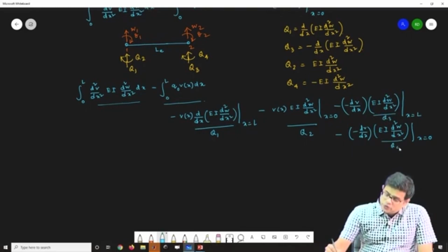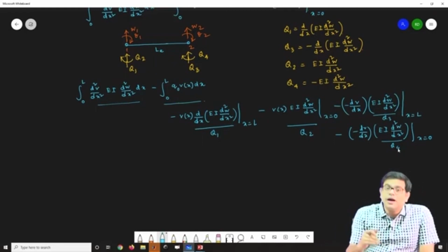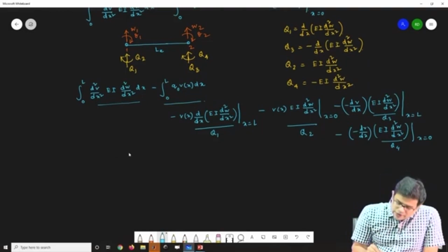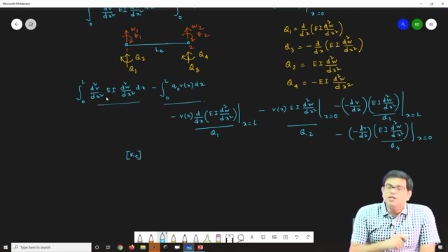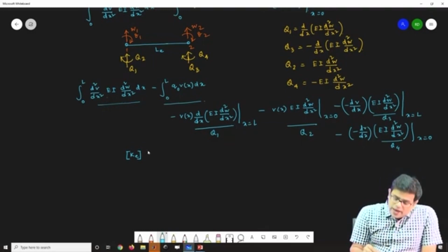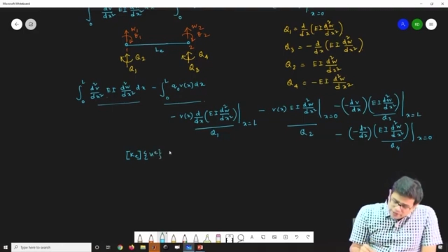The objective is, if I discretize, substituting the shape functions, or the beam shape functions, I will get something like this: Ke, which will be coming from here. That is the shape function stiffness matrix, and then I will have the variables. Let me say UE. UE I will define, and then this will be equal to my Fe.